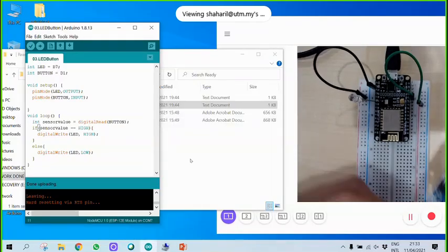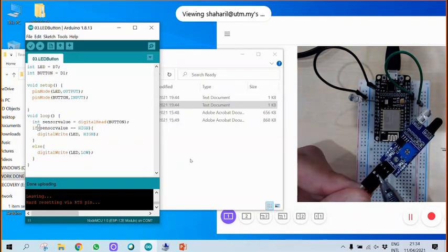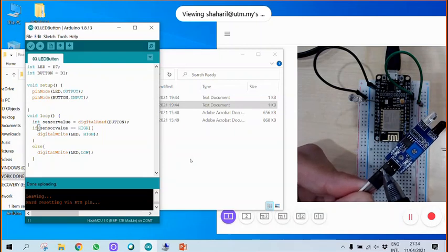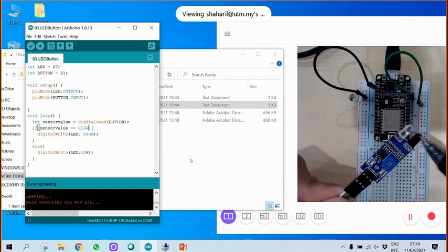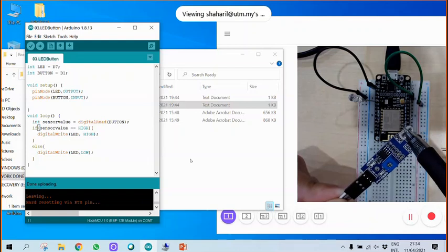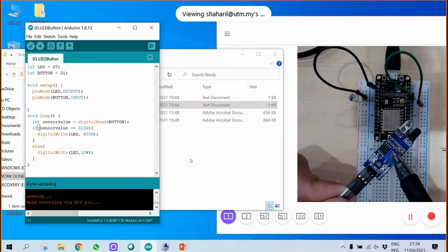Okay. So this is the IR module, right? The output from this module will be digital, whether 1 or 0, whether 3.3 or 0 volt. This one we call it the module. This one we call it a sensor. It has the transmit and it has the receive. So if you buy only the sensor, we call it a raw sensor, only raw, right? Only the sensor.